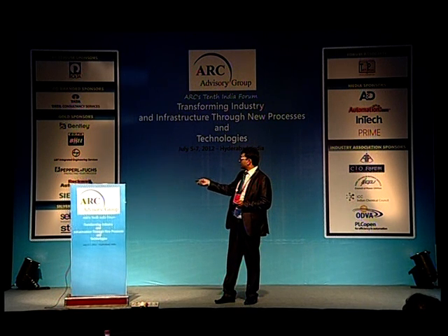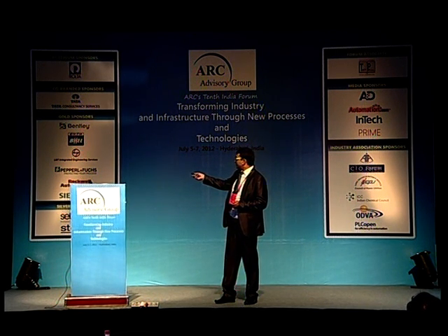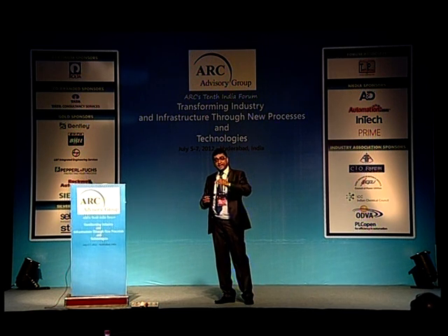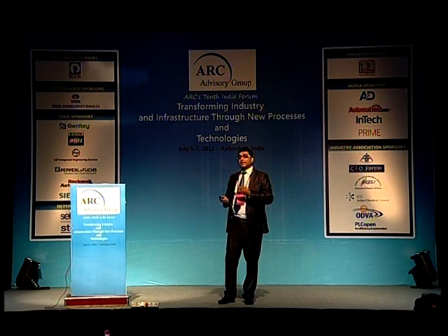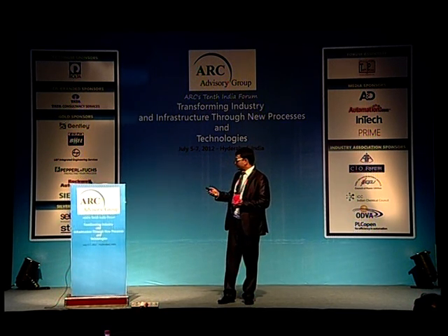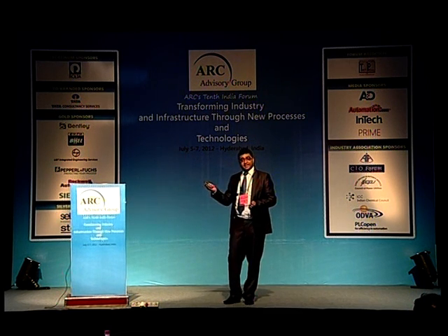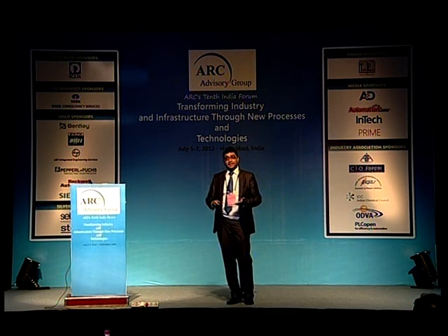And in the previous slide, if you see, there is a yellow color. Yellow means you have to wait. So it's in the queue. Once the red is completed, then you will go to the next step. So it doesn't give soot blowing advice simultaneously. A lot of operational constraints are taken care of by the system, which is configurable and very easy for the user to change.